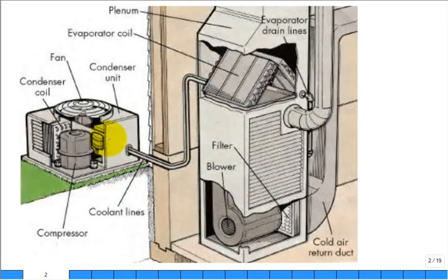Here's a blow up, a cutaway. So here is where the compressor's at. This one looks like it's a hermetically sealed compressor. Usually if they're a little bit slender and taller, there'll be a scroll compressor. This one looks like an old traditional reciprocating compressor, piston sliding back and forth in a cylinder. Then it goes to the coils. The coils would be wrapped around, they try to wrap it around 3/4, if not more, of that box. But usually you have some service panel and some where the lines come in and out and the power comes in and out. So it can't be 360 all the way around.